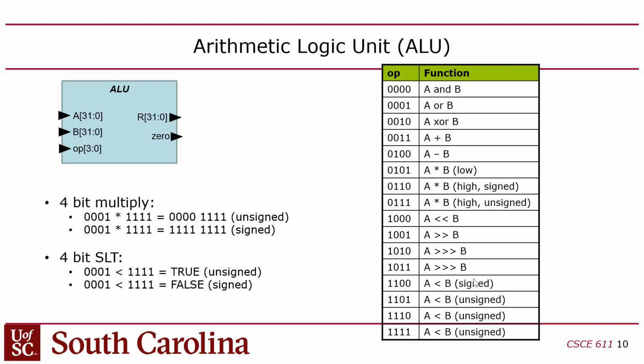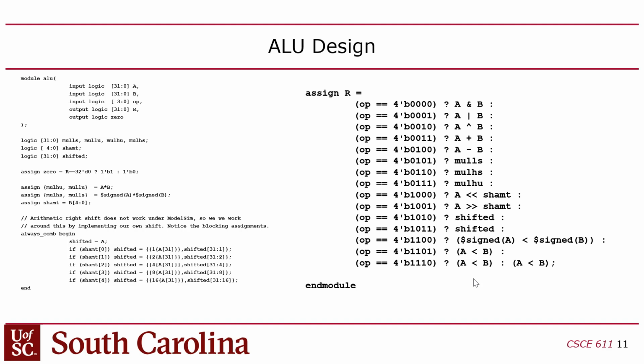Okay, so basically there's, in the RISC instruction set in MIPS, one R-type instruction for each of these operations. And then some instructions use these indirectly. Like, for example, a branch instruction will use the comparison, even though you're not doing a set less than, you're doing a branch, but the comparison opcode is used to resolve the branch. Make sense? Okay, so mostly these ALU functions are used for R-type and I-type arithmetic, logical, shift and comparison, and number crunching instructions.